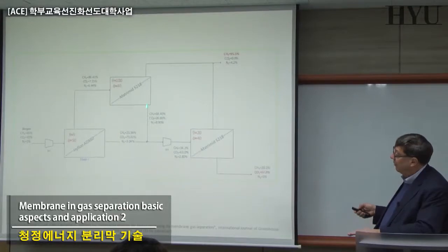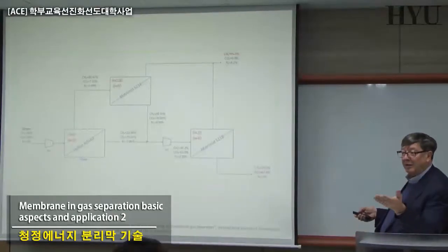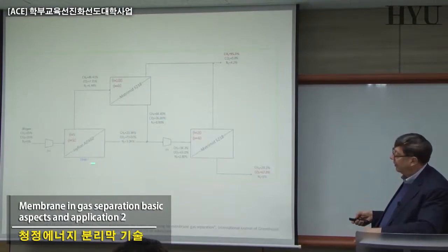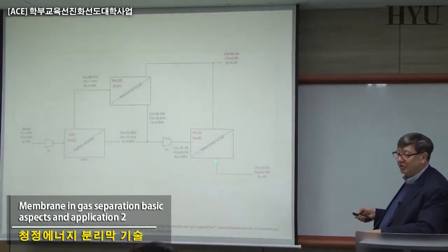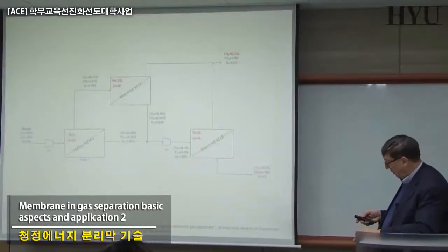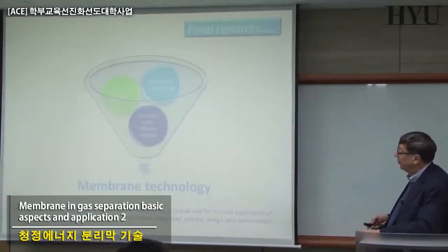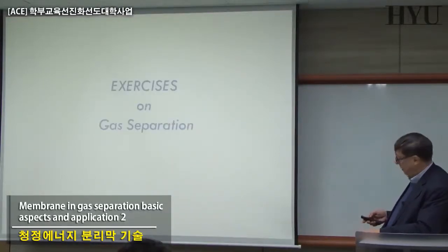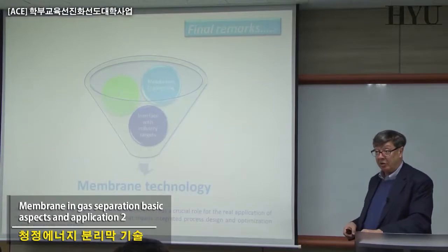So with the existing membranes, as we are doing today in reverse osmosis, in one step you can do everything. In gas separation, at least 3 if you want to work on CO2 methane, which means there are a lot of opportunities still to look for, to improve the membranes for gas separation.